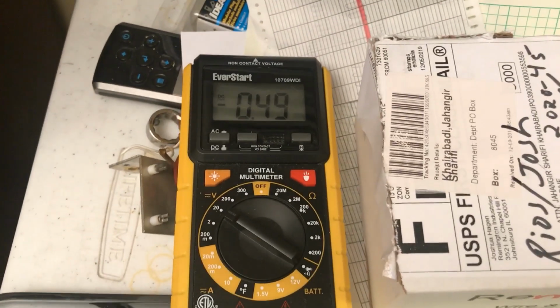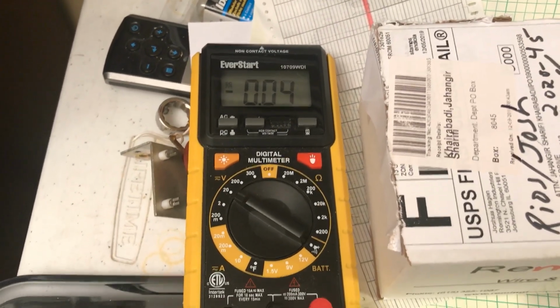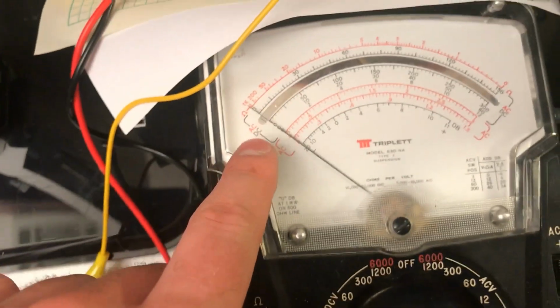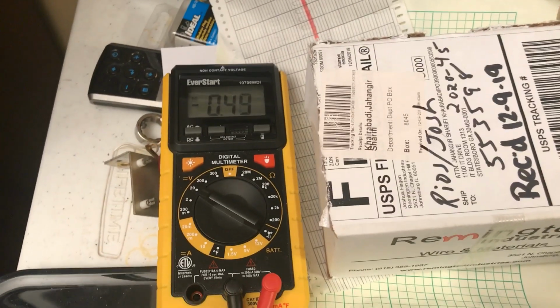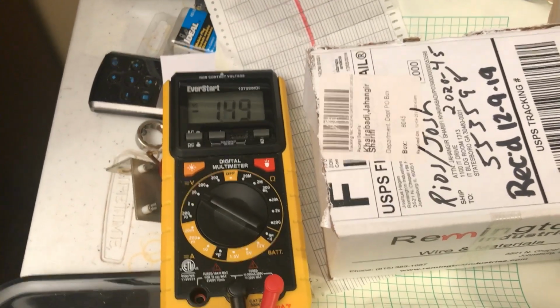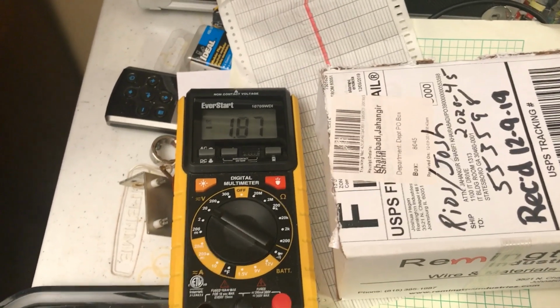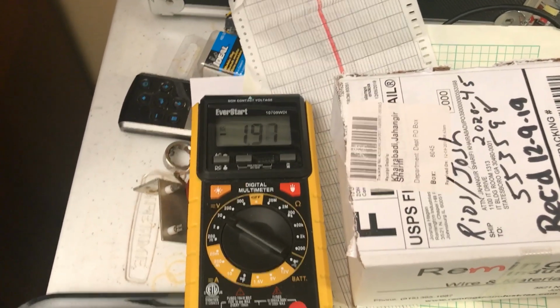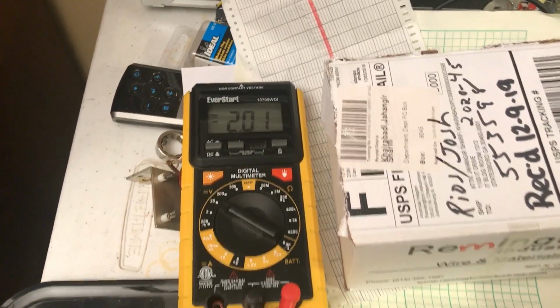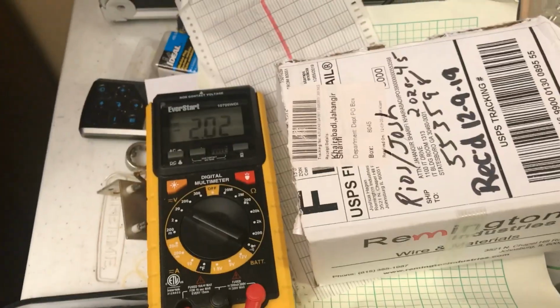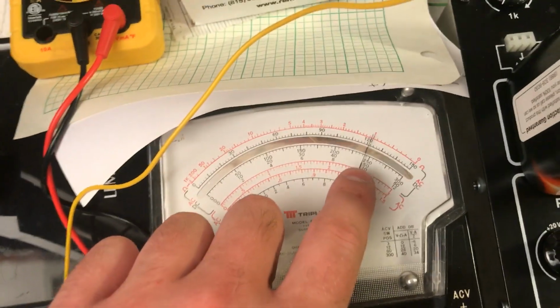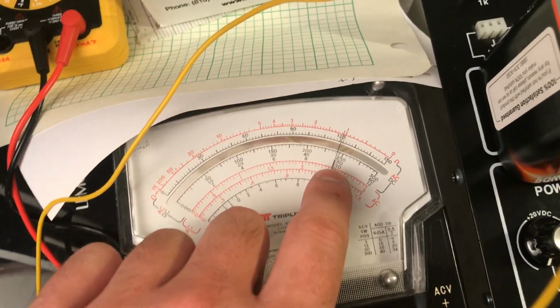Okay, we can also do larger values. 0 zeros it, as you can see, a little bit of back bias, and let's increase this thing. Let's go all the way up to, well, 3 volts would be off the scale. Let's do 2. And you can get really precise with it. That's pretty close. 2 volts times 5 would give you 10 volts, which you can see right there is what it gives. It works. It amplifies direct currents.